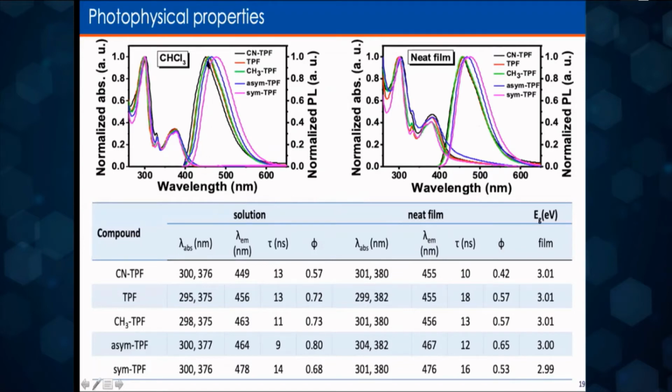So we get a wide bandgap semiconductor, but you see that organic materials often have a color purity problem. Most of the tails are popping into the green part of the spectrum. So the challenge still is, how are you going to make it blue, with a very, very narrow emission?